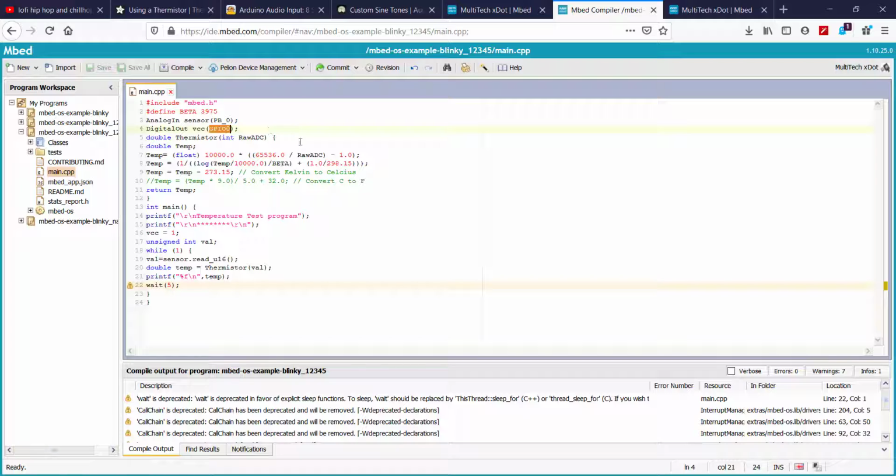The code, as I discussed previously, this is the code. The main logic is in this function: read, pass it to the thermistor function, convert it to the corresponding temperature using the formula, then convert it to degrees Celsius from Kelvin, and just send it over the UART.